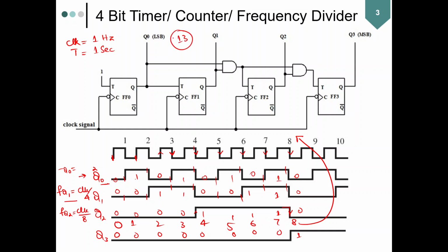So what should we do? All we need to do is give it this clock and count the number of pulses till 13. Once 13 pulses have been counted, it would mean that 13 seconds have passed. At that point, we just do the action we want to perform through some interrupt, through some code.